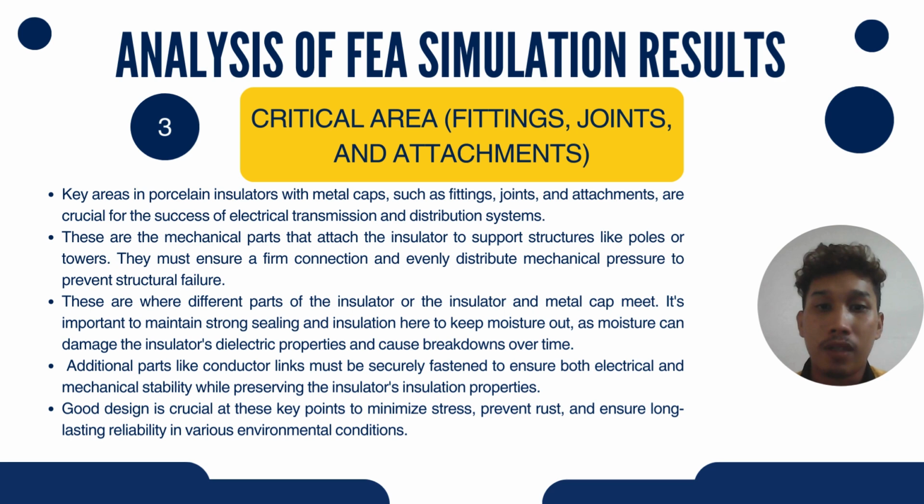These are where different parts of the insulator, or the insulator and metal cap, meet. It's important to maintain strong sealing and insulation here to keep moisture out, as moisture can damage the insulator's dielectric properties and cause breakdowns over time. Additional parts like conductor links must be securely fastened to ensure both electrical and mechanical stability while preserving the insulator's insulation properties. Good design is crucial at these key points to minimize stress, prevent rust, and ensure long-lasting reliability in various environmental conditions.